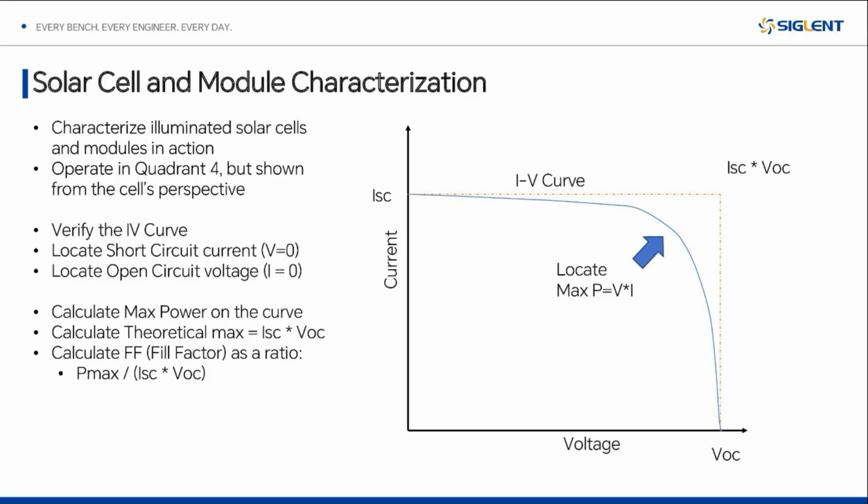So another important device here, and worth knowing that this graphic is typically shown like this, right? But it's actually happening from the instrument's perspective in quadrant 4, right? Because this device is delivering current to the instrument. So the instrument sees that as negative current at positive voltage.